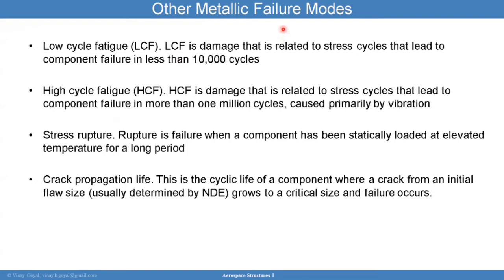Let me cover now low cycle fatigue. Low cycle fatigue is damage that's related to stress cycles that lead to component failure in less than 10,000 cycles. Low cycle fatigue failures are basically repetitive damage. You're applying repetitive cycles at a very high loading condition, and that high loading condition will cause failure at a low number of cycles.